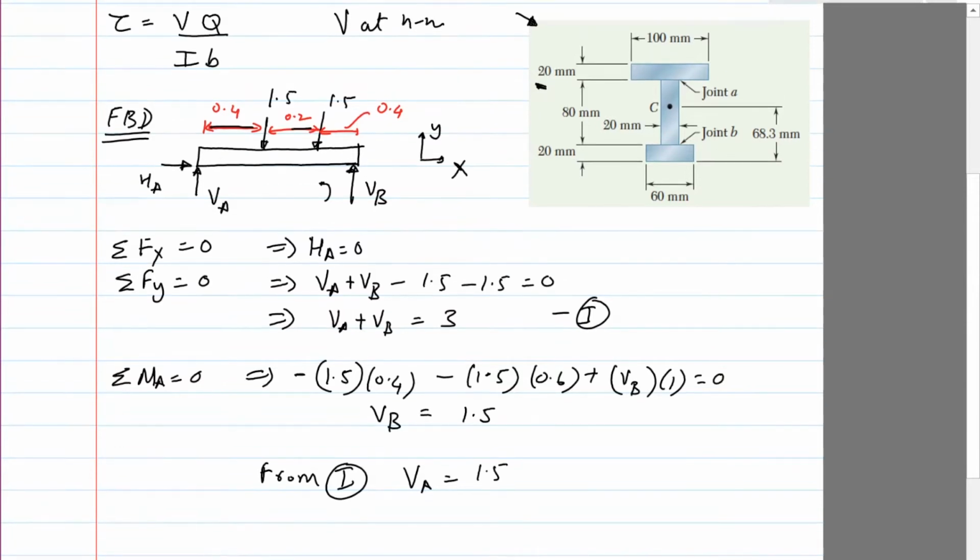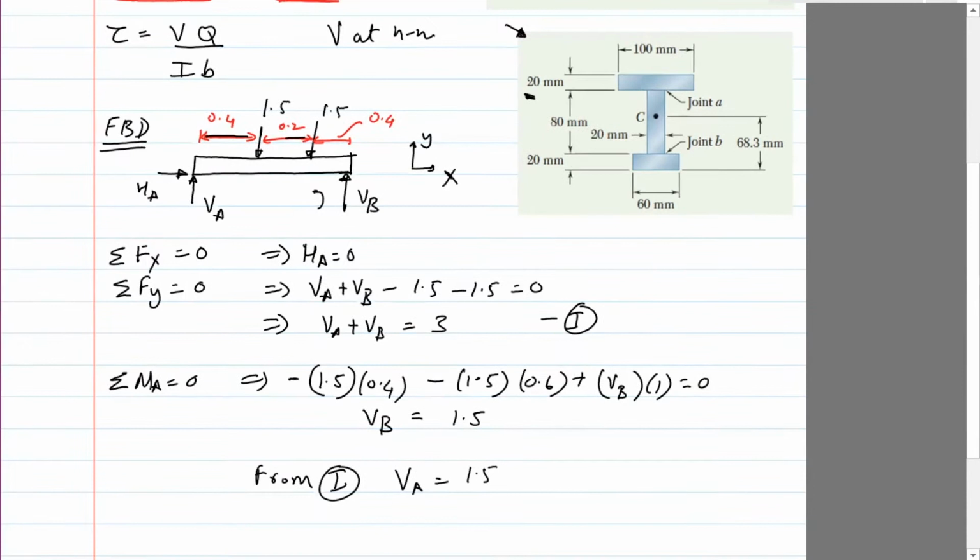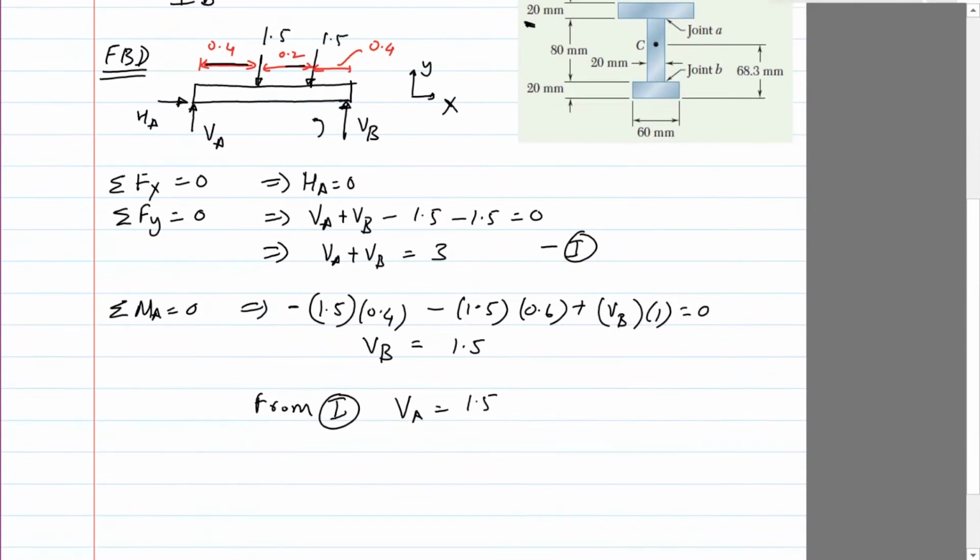Okay, so it's not actually surprising. I didn't notice this, but this is what is commonly known as 4-point bending loads, which means that if you draw the bending moment diagram, you'll see that the bending moment is constant from that 1.5 on the left to 1.5 on the right. One of the diagrams I drew earlier. And this doesn't come as a surprise, actually. We could have found this by inspection. We didn't have to do all the math.